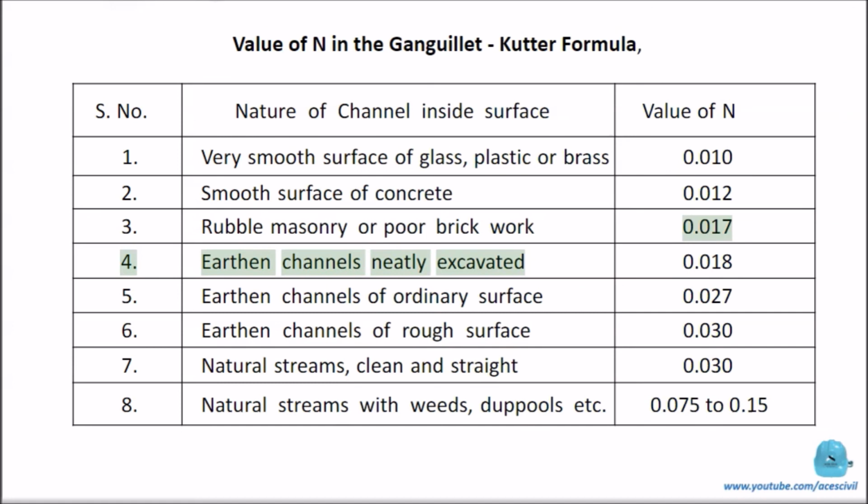Earthen channels neatly excavated, 0.018. 5. Earthen channels of ordinary surface, 0.027. 6. Earthen channels of rough surface, 0.030. 7.